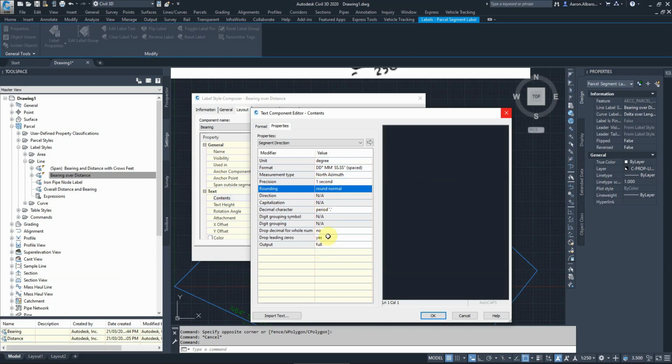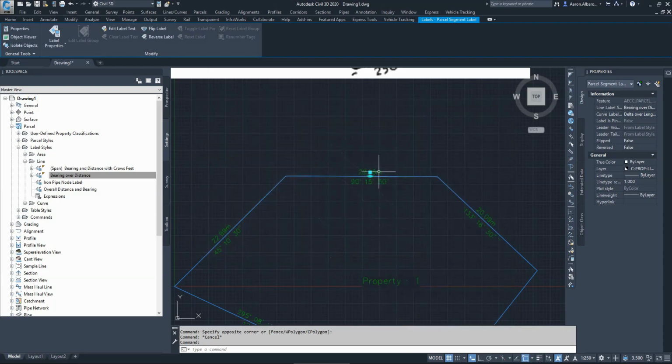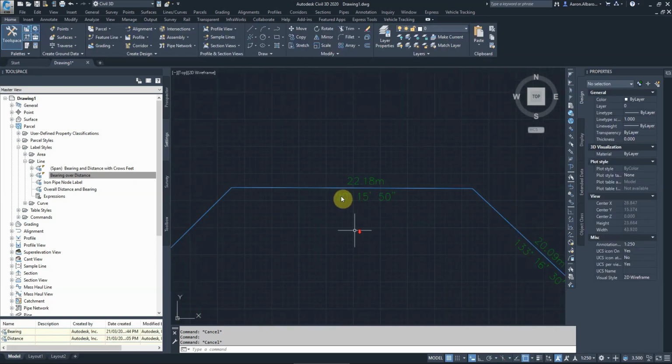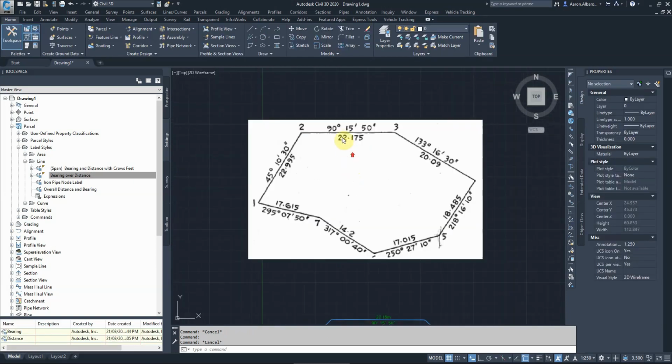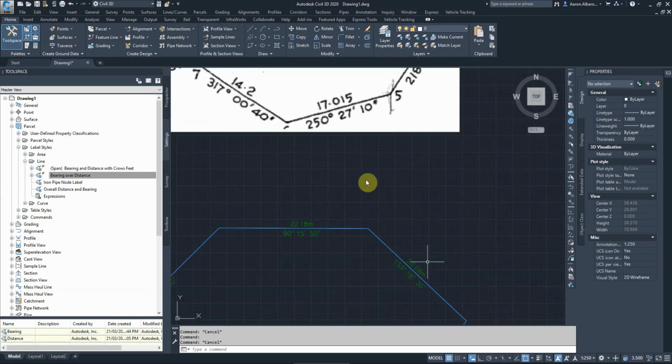Before you exit here, you haven't finished. Don't forget to click on this arrow, because we deleted our settings and I need to add the new settings. Now I've added the new settings, go OK and apply, and these should change. Look at them now. That's exactly what we had, 191550, and that's 191550. That's 133.16 and 30, 133.16 and 30.